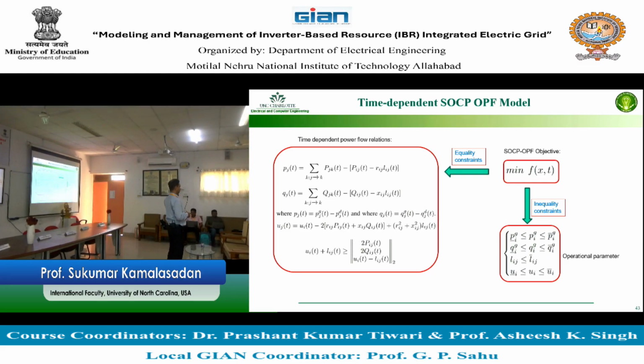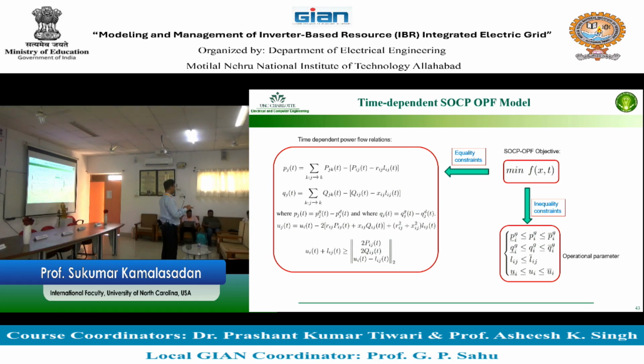But for a distribution system, many times it is not fixed. You know why? Because in a distribution network you always try to open a switch, close a switch, some maintenance happened. So the topology is not fixed all the time. So it may be changing. So it's important to understand in which topology you are working.